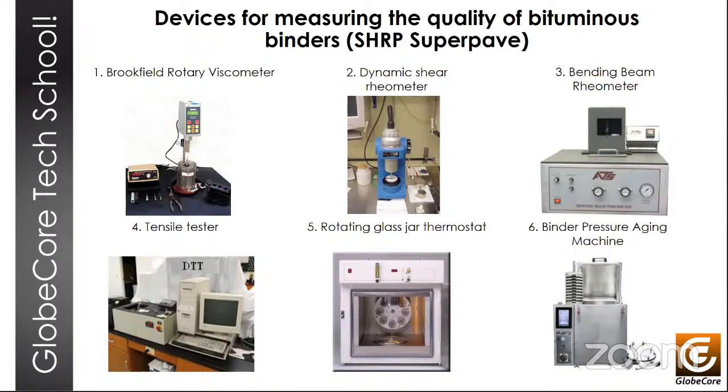So the advantages of the SuperPave methods include the following. Application of fundamental physical and mechanical characteristics of the binder, a uniformity of requirements for various types of binder, the relationship between the requirements and the actual operating conditions of the road layers. It gives an accounting for the aging of the binder and accounting for the process of its preparation and operation as part of the asphalt concrete pavement, and the use of computer technology in research and processing of results, which provides for quite precise measurements.